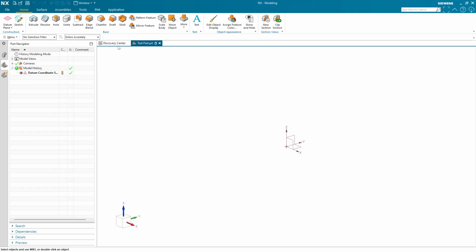Moving into the fun part, as we scoot on over to our workspace, we have this viewfinder down in the corner. So if I hold down the middle mouse button on my little icon there, you can see I'm rotating my view. If I continue holding down that middle mouse button and right click, I start panning around. So I start sliding around our part, which we'll see in a little bit. If I need to snap to a certain view, so one of these faces, I can click on it like that, or like that to move around a little bit.